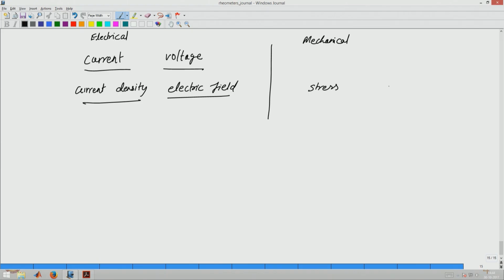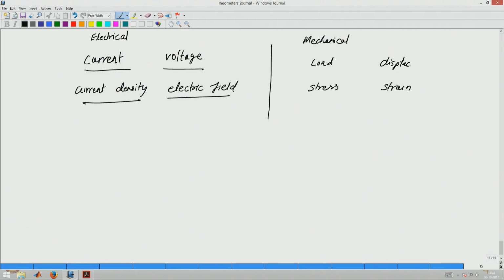In fact, the material behavior is defined in terms of stress and strain, but when the measurement is done, what is it done with respect to? Load, right. So, we generally will measure load and then displacement, load versus displacement curve we will say sometimes, or deformation. Deformation will still imply that we are processing the data and dividing by the original length, but displacement is basically what is being measured.